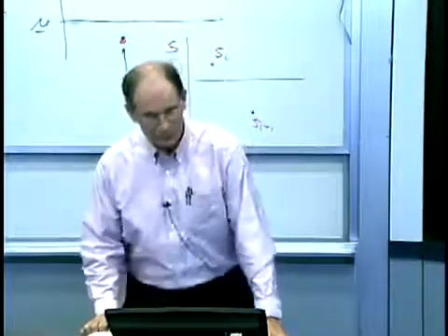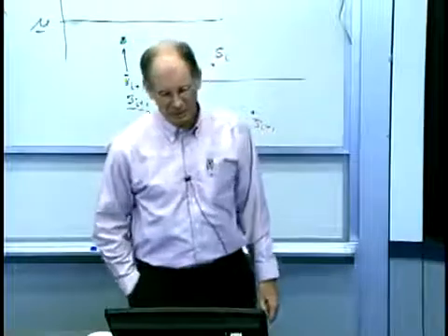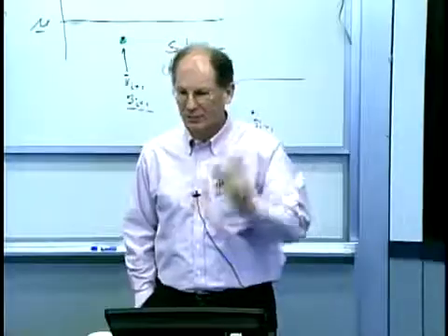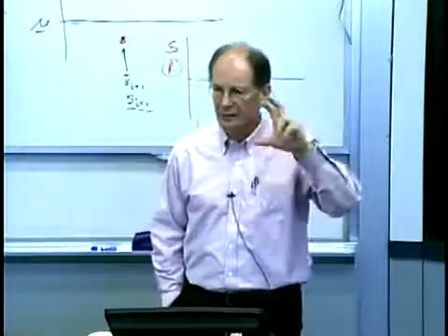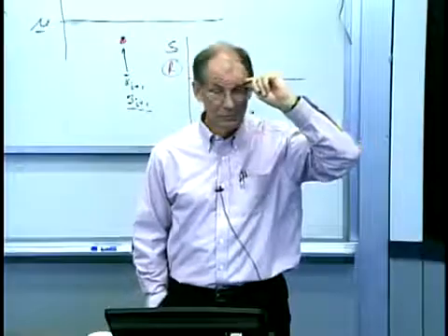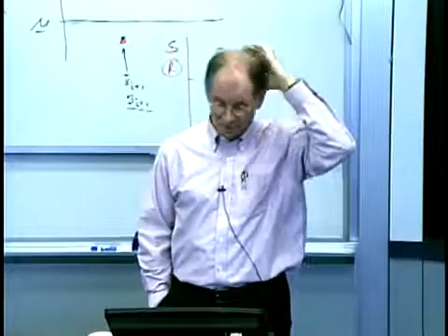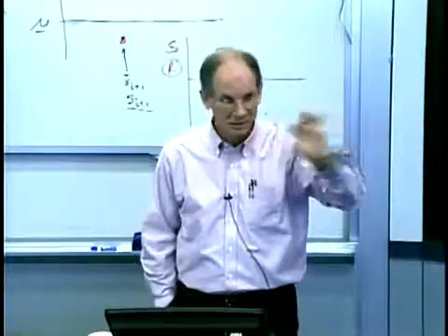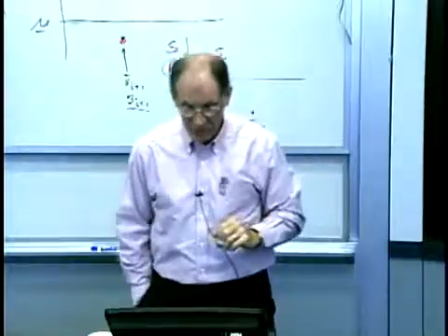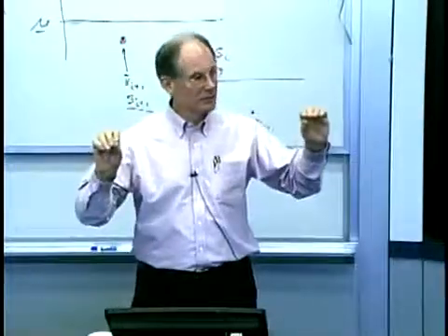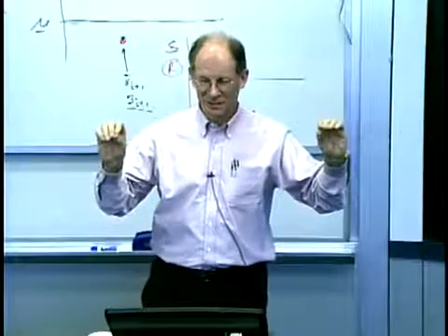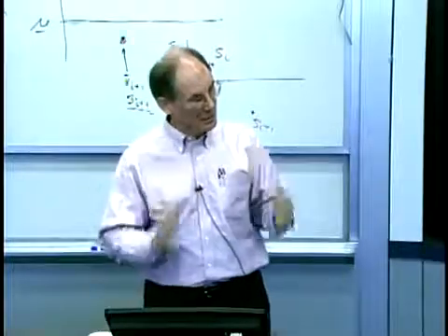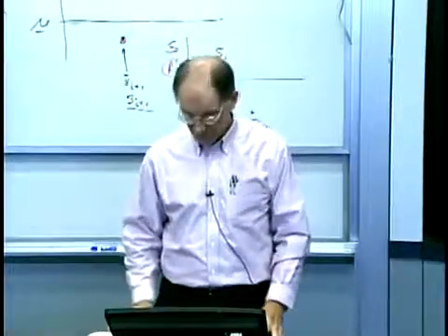Improbable points. Now, they've quantified this by saying, if I look at any triad of points, and 2 of 3 of those are in the plus or minus 2 sigma band, that's pretty improbable based on confidence intervals. 4 out of 5 outside the plus or minus 1 band is also pretty improbable. Or all the data inside the plus or minus 1 band. That shouldn't happen either if my process is stationary. Each of these could indicate that it's not following the expected normal behavior.